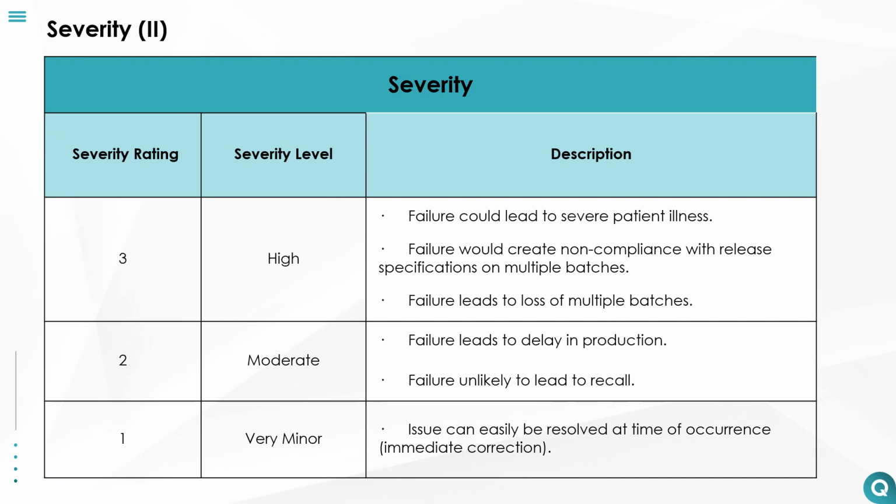A severity rating of 2 would include something such as a failure of a labeling machine, leading to some vials being labeled with smudged batch numbers that were in some instances difficult to read. This issue was identified during QC checks before batch is released. The affected vials would need to be relabeled, causing a temporary delay in release of the batch. However, there is no impact on the efficacy or safety of the drug itself. The inconvenience and potential minor delays in production or release would warrant a severity rating of 2. If there had been an incorrect drug or concentration labeled, this would be a very serious incident, potentially requiring a